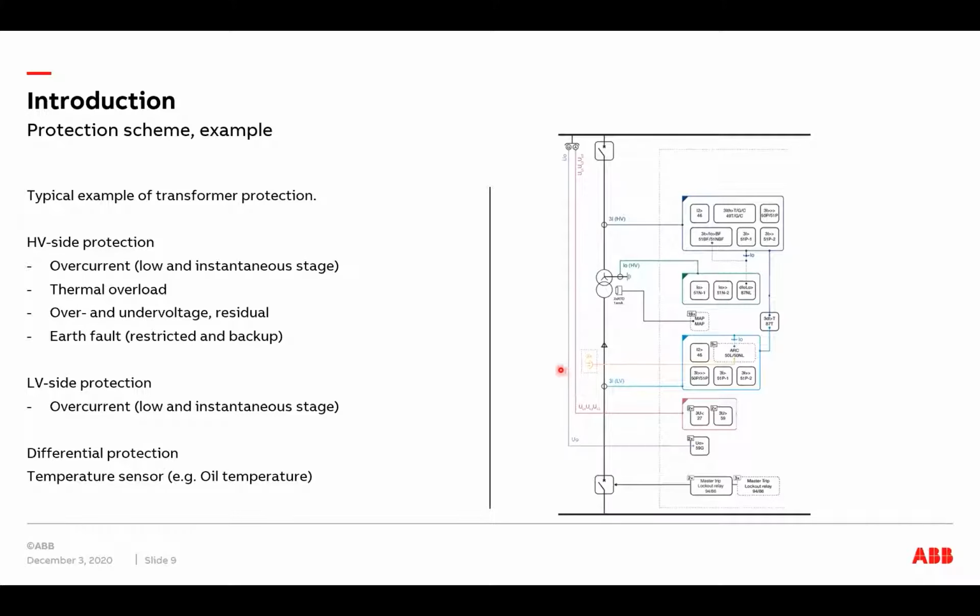So from the high voltage side, first of all, we will usually have overcurrent protection, a low and an instantaneous stage. We can also have thermal overload protection, over and under voltage protection, and also over residual voltage protection.